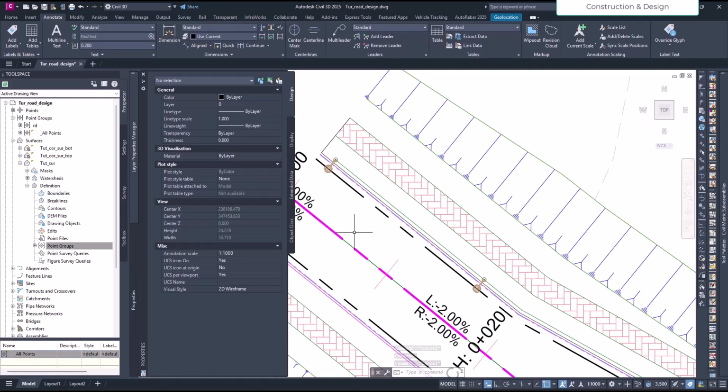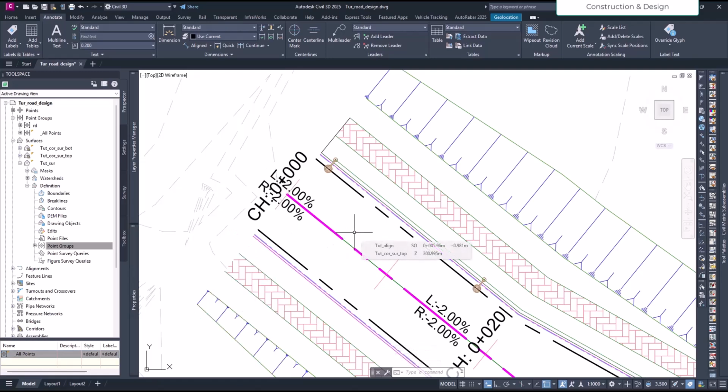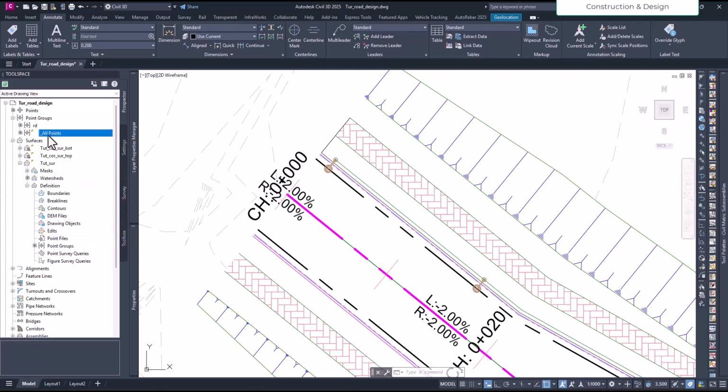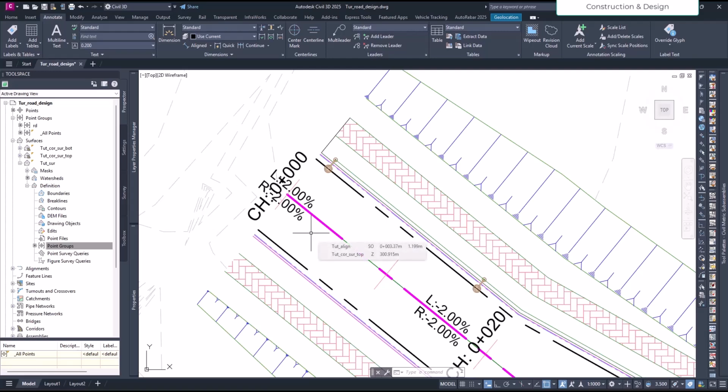So if you have something like me, you can create a group with all those points, remove this, and add that to your surface rather than keeping all the points for the surface creation. For that, let's do something. If you don't have that issue, you can skip ahead in the video to the next step.